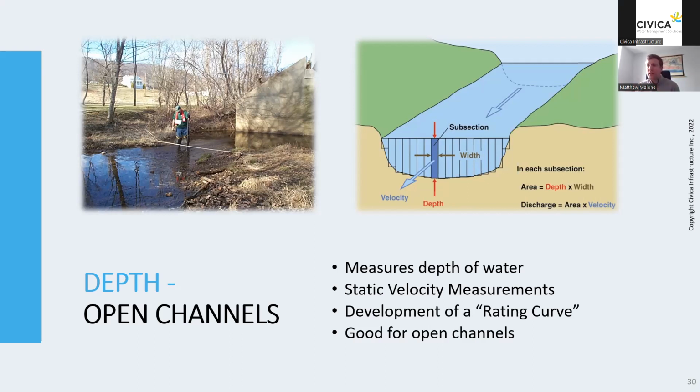Some conservation authorities have in-channel depth sensors, pressure sensors, or sometimes bubble sensors, things like that. So this is measuring the depth of water, and then we typically go out and measure static, or point-in-time, velocity measurements. You can do that during low flow conditions, at various flow conditions, up to as high as you possibly can safely, ideally, to develop what we call a rating curve. And as you develop this over time, it will give you an understanding of the relationship between the depth and the flow at a particular point in, let's say, a culvert or a river system.